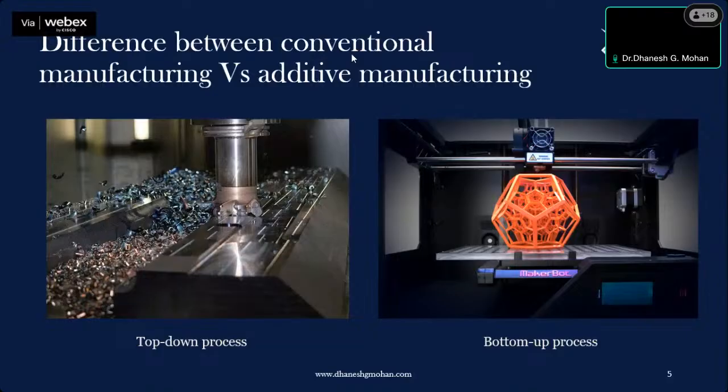And you may think that metals we can recycle, right? But the problem with metal is that we are using different kinds of coolant, different kinds of medium over there. So it's nearly impossible to recycle, because we need to wash and prepare those for recycling, and the recycling process itself is highly expensive compared to producing new material from ore. So people are not considering recycling those materials.